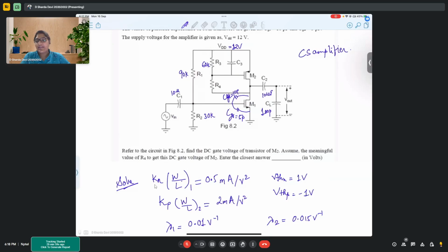So you can have metal, semiconductor and highly doped regions, like if you have a substrate with source and body grounded, then you have this MOS capacitor, right? And you also know the value of the MOS capacitor. So from there, that particular configuration can be used as a capacitor inside the circuit if you want a capacitance. So, can we obtain large values using transistors, like 90K or in mega?